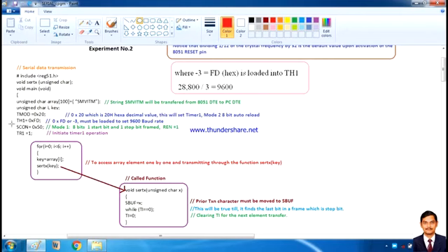A timer is mainly built to generate a delay. Now by moving 0x20 to the TMOD register, where x indicates a hexadecimal value, this will set timer 1 to mode 2, 8-bit auto reload.